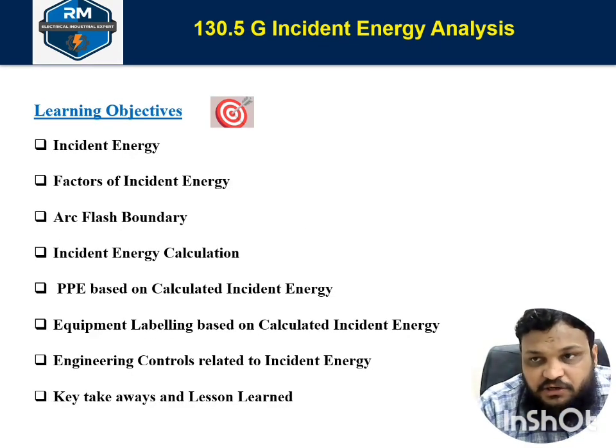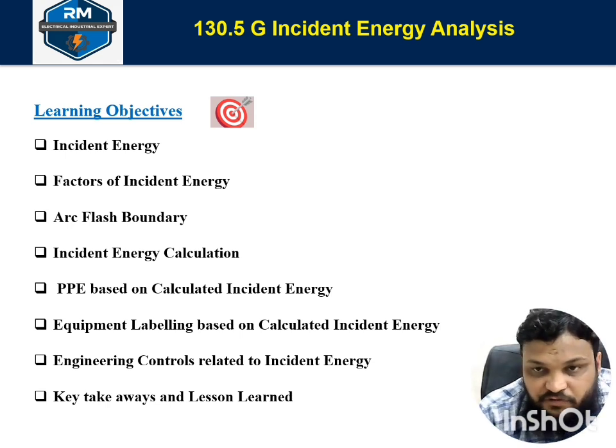Now, in today's session, what we are going to learn is incident energy analysis. So we are going to discuss what is an incident energy, then factors on which incident energy depends, then we are going to discuss arc flash boundary and calculate incident energy. Then based on calculated incident energy, we are going to discuss how we can select PPE for arc flash hazards.